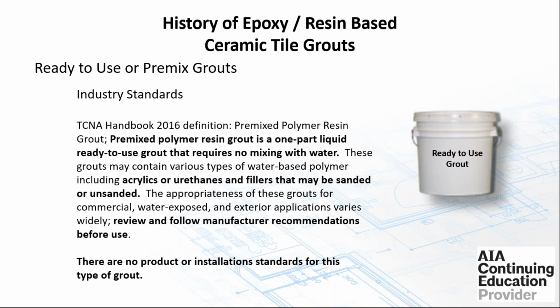The standard on these ready-to-use grouts is that they're a polymer resin grout. It's a one part ready to use that requires no mixing with water. They may contain various water-based polymers, including acrylics or urethanes, and fillers that may be sanded or unsanded. The appropriateness of these grouts for commercial use or water exposure or exterior application varies widely. So check with the manufacturer of these grouts before you start saying, I can use this anywhere.